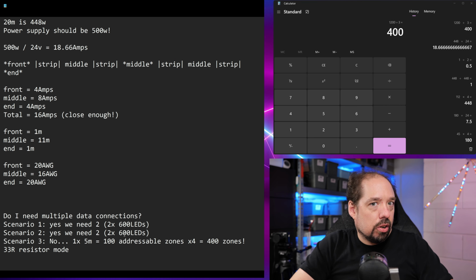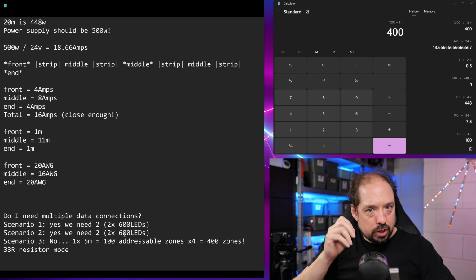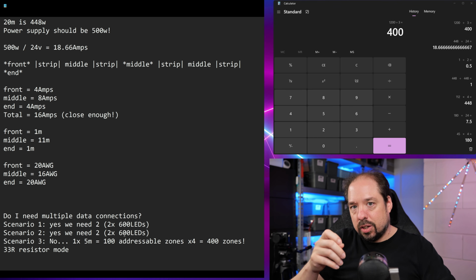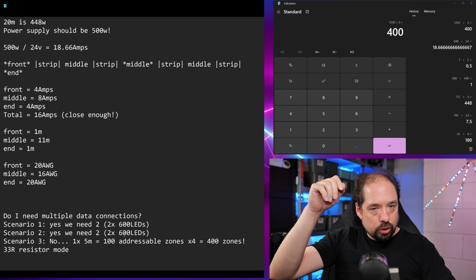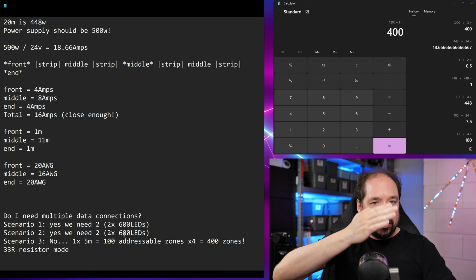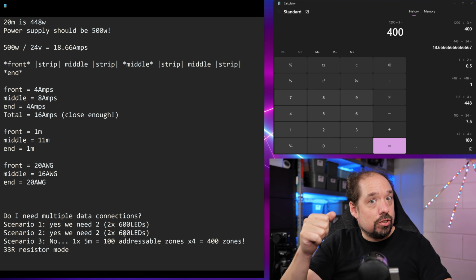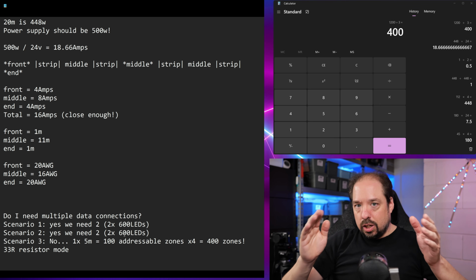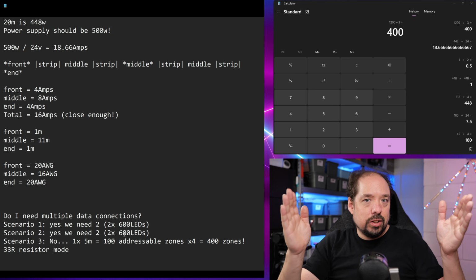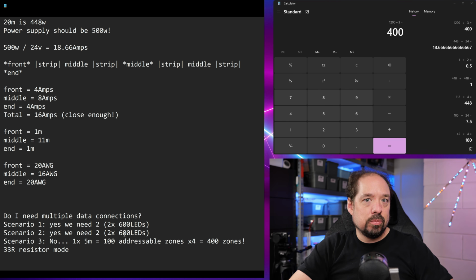And if this is a long length, I recommend running 2-wire cable, so with the data signal and ground together in that cable, to the front of the third LED strip, have the data cut there, and basically inject data there from the second LED channel to keep those 1200 LEDs in total running at a nice and good frame rate. Hope that makes sense.